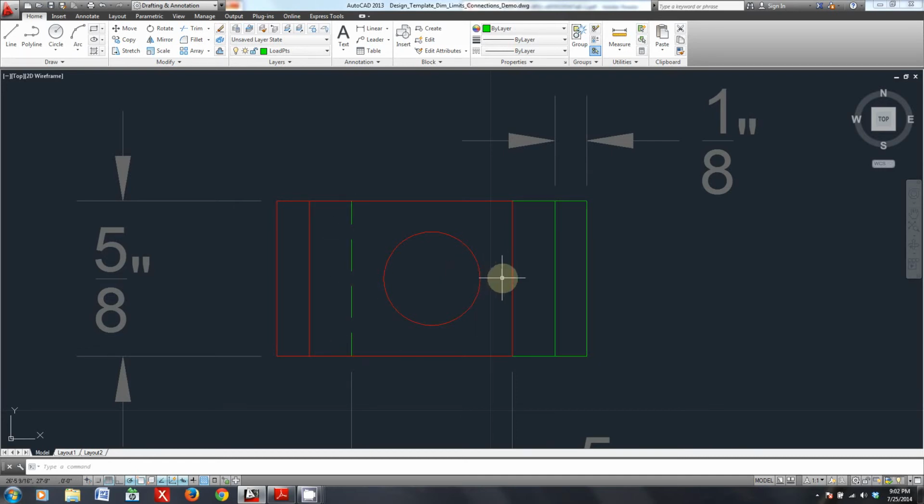So how do we decide what this dimension should be, here to here? There's probably a number of ways you could do this. One way would be to reference some of the notes from your trusty steel design class for bolt design. As you probably recall, there are two main failure modes for bolts, one being bearing and the other being tearing. So you could use some of your design equations from that to get rough estimates of how much you would want this dimension to be, and likewise this dimension. You could even do some rough calculation of net section for these areas.